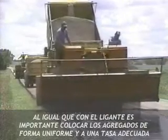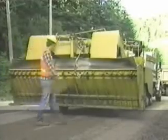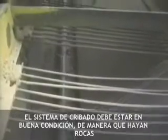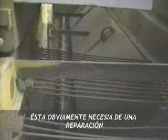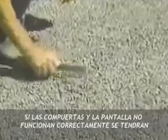As with the oil, it's important for the chips to be placed uniformly and at the proper rate. So check the gate controls and look inside the hopper. The scalping screen should be in good repair, so that no large rocks or debris will block the gates. This one obviously needs some work. If the gates and screen do not function properly, you'll end up with either too many chips or not enough.